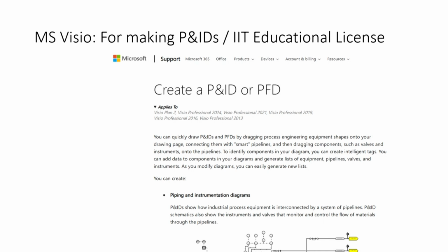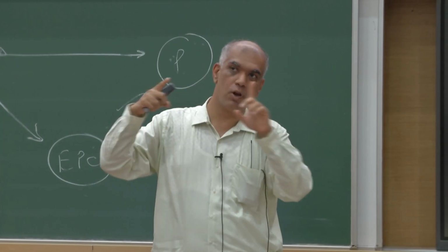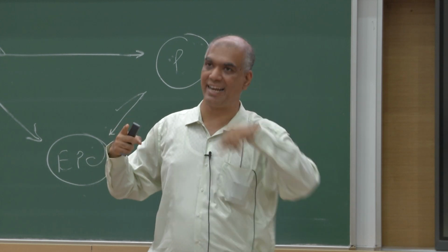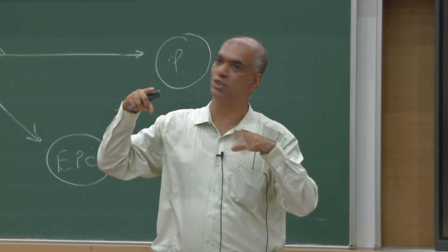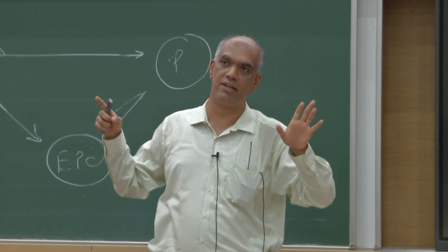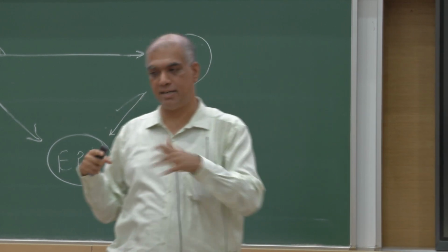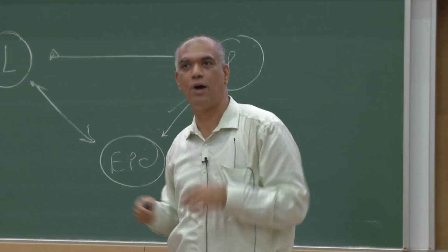But if you want to do a good P&ID, and what's a good P&ID? So lines shouldn't intersect, right? And that's quite difficult to do in things like PowerPoint. If you try to do a complex P&ID in PowerPoint, sooner or later your lines intersect. In a good P&ID, lines will always break where they intersect so that you can trace them, right? And not even the circuit sort. You don't do those loops on a P&ID normally, you break lines. And things like Visio will do those auto routing and things like that.